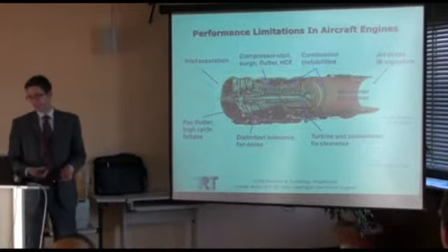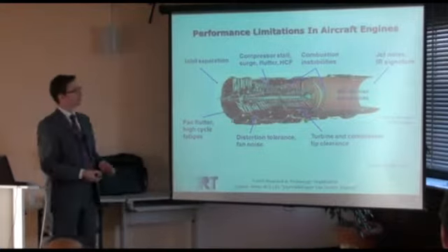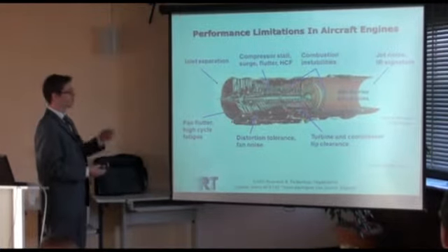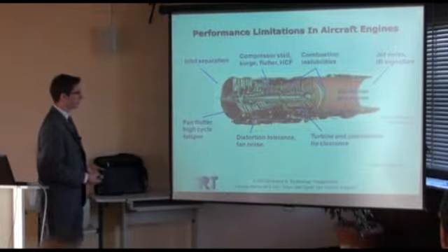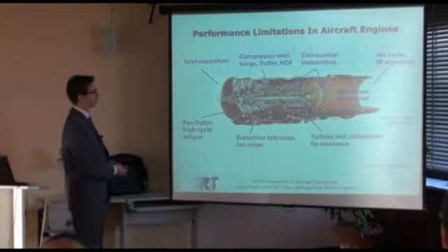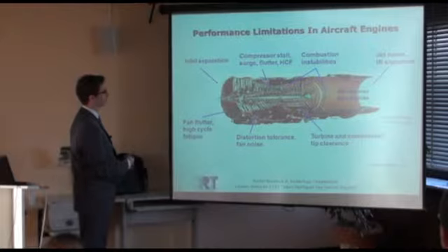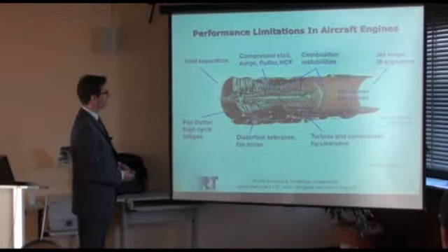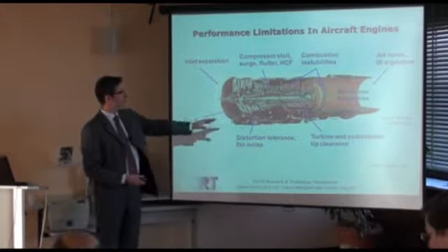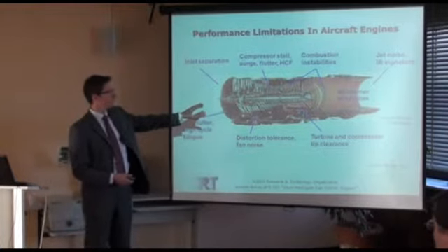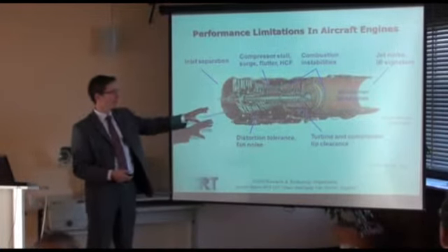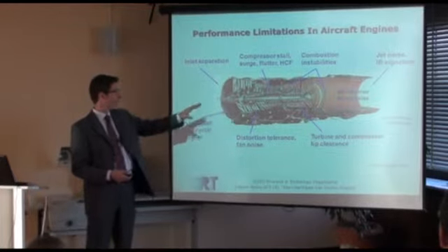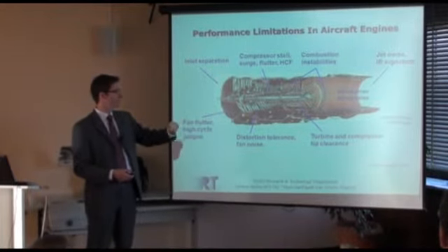So again, as an introduction, I would like to show you the performance limitations we have currently in aircraft engines. Maybe you remember some of them from my presentation yesterday. We've got inlet separation, stall and surge in the compressors, combustor instabilities, afterburner instabilities, noise, and all that's associated with that.